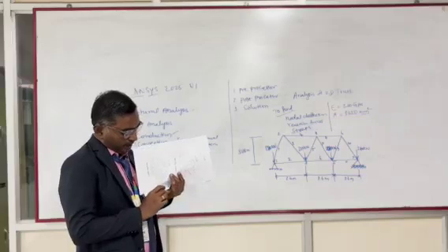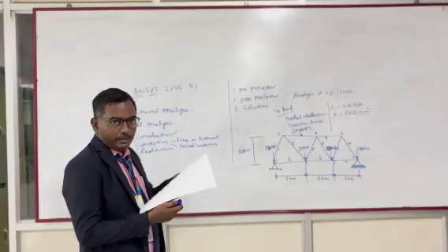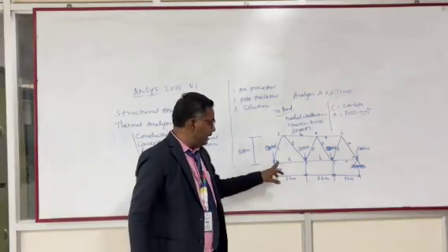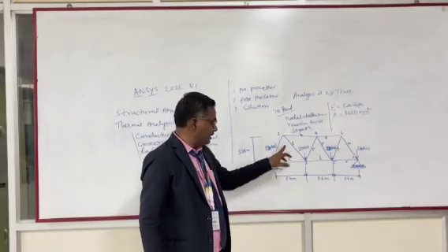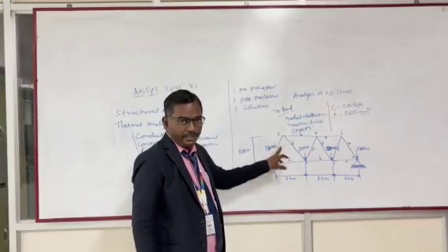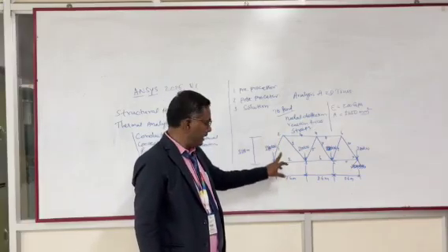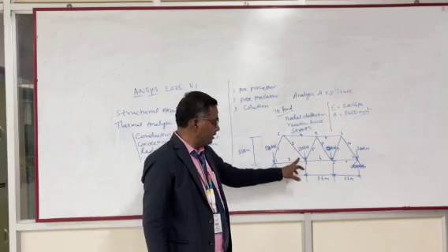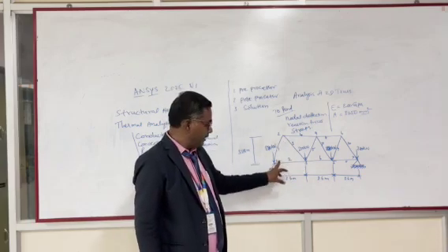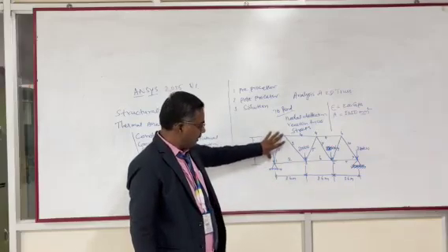So in this problem, Ansys treats it as a truss problem. For this type of problem we use only the given number of elements. Each element we can divide when we are going for meshing, but in the truss problem alone we have to take a single element. These are all single elements, so you should not divide these elements.